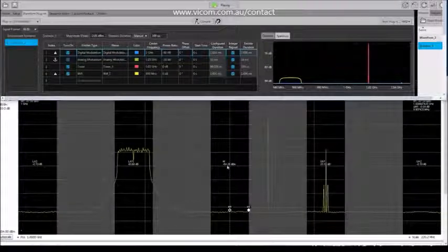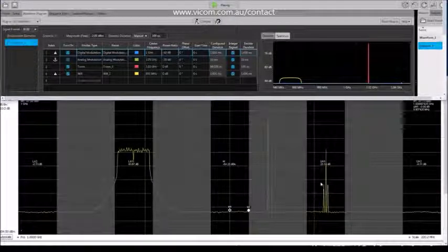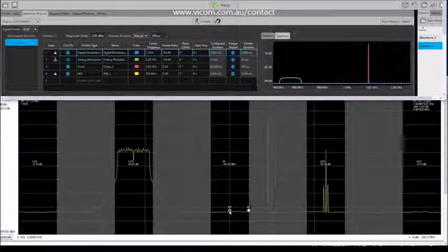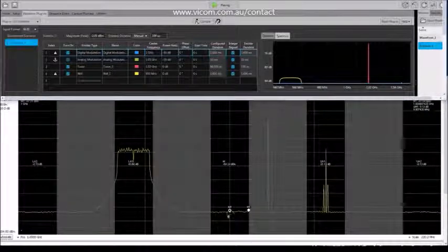So right now we're just outputting this one signal out of one channel of the AWG. So what we can do is put this out of both channels of the AWG, put it through a combiner so that we are using the full range of the 2 DACs in the AWG. So we get a much higher dynamic range capability. So let me go ahead and configure that real quickly here.